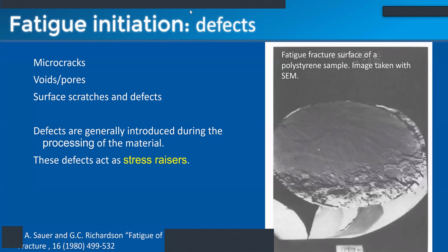The other thing that complicates fatigue testing is that fatigue failure is very variable. And you can think about why that might be, because we talked about what causes fatigue failure. It's the presence of little surface defects, cracks, and things like that, which are different from device to device. If you've got 10 devices and you do fatigue testing on all of them, some of those devices might fail at only 10,000 cycles. Some of them might fail at 100,000 cycles. It's going to be a very broad distribution.